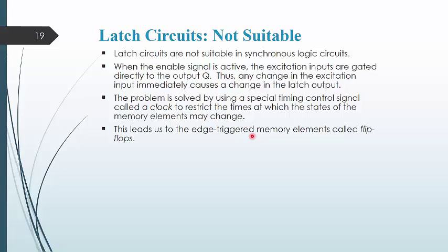But the problem is that the latch outputs are present only if the gate input is high; otherwise they do not change. To solve this problem, we apply a clock input signal instead of the gate control input signal, and we will cover that in detail in the next lecture on flip-flops.